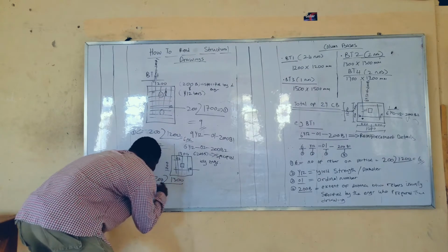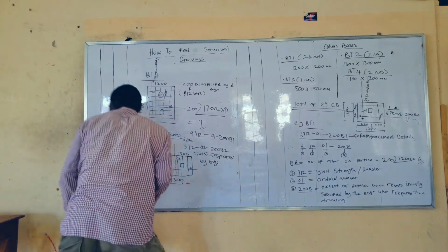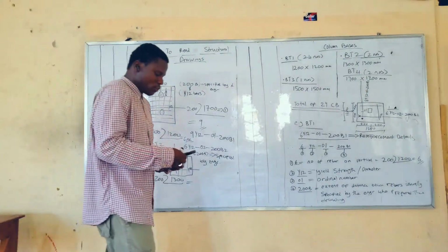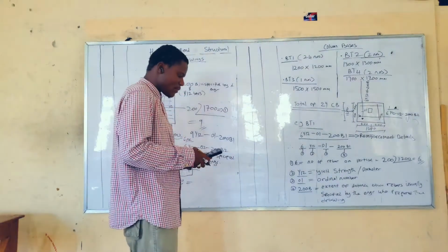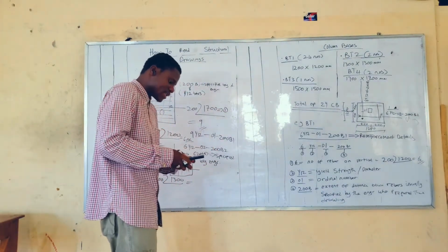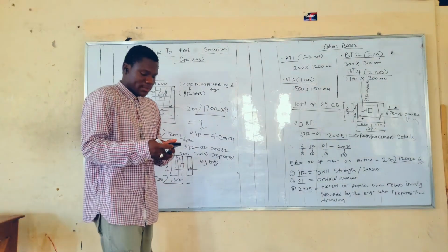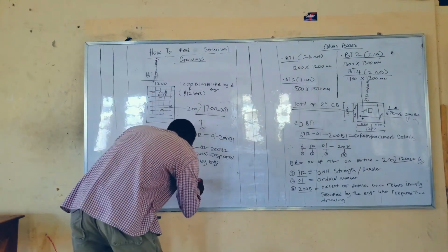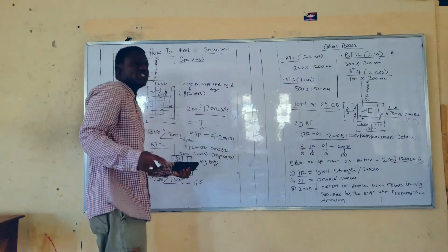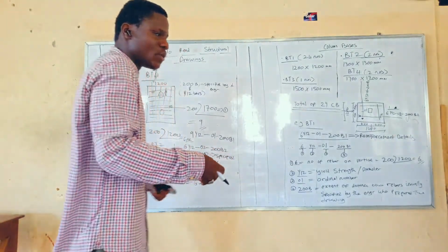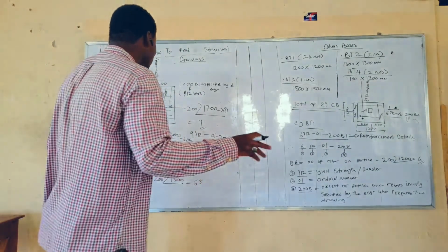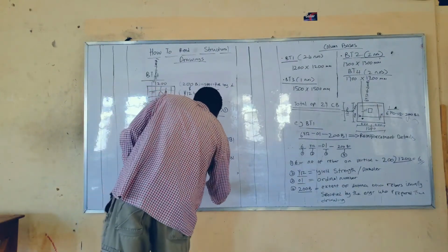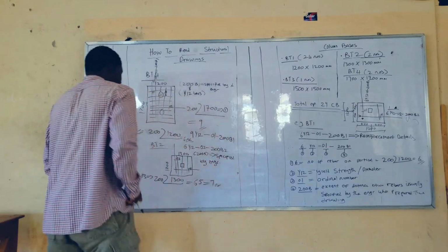So that would be 1300 divided by 200, which will give us what? Let me use my calculator. Always use your calculator because once you put the right numbers in the calculator, it will never make a mistake. But several things can make you make a mistake if you're using your mind. The answer is 6.5. And obviously, there can't be 6.5 bars. We're talking about structure, so it cannot contain any kind of weakness. So we'll round it up to 7 numbers required.